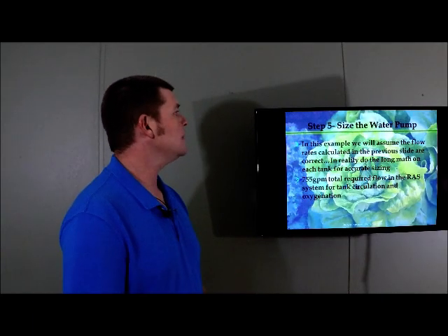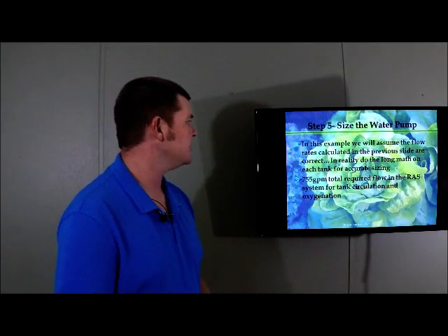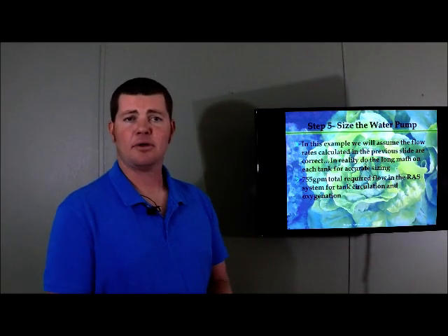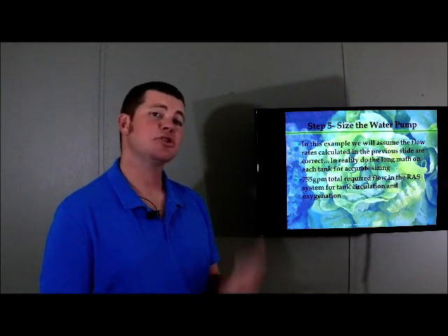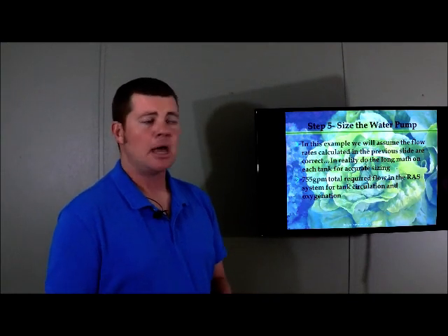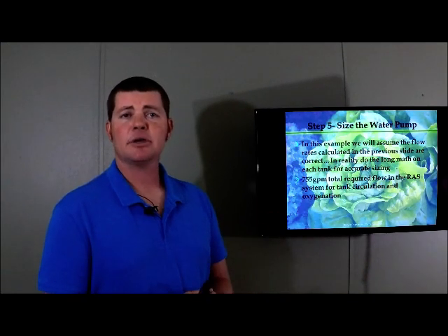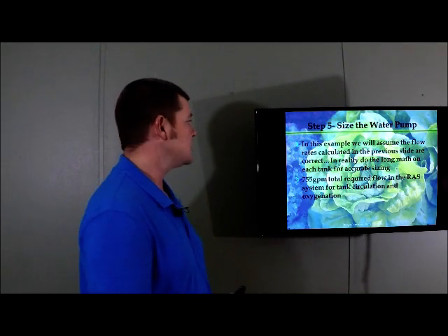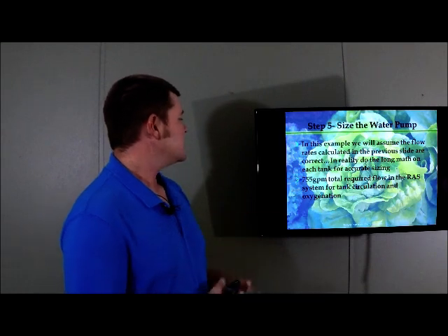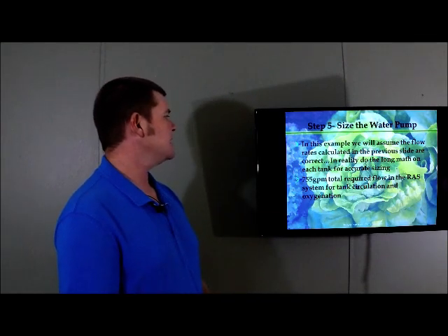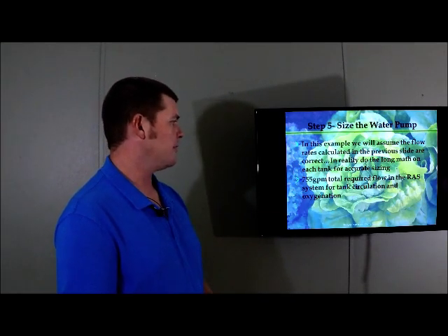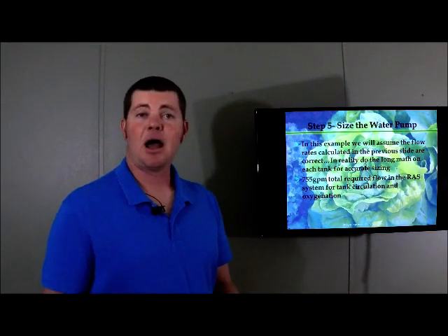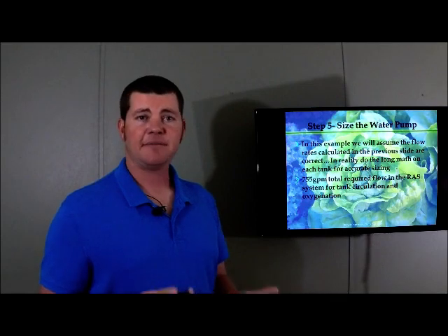In this example, we will assume the flow rates calculated in the previous slide are correct, okay? Because I didn't go through and do the long math on all the other smaller size tanks. So we're just going to assume those percentages are correct. But for the 5th time, I'll tell you, go back and do the hard math on each of those tanks because the numbers will differ slightly. 755 gallons per minute is our total required water flow rate in the recirculating aquaculture system for tank circulation and for oxygenation, which is our limiting factor.